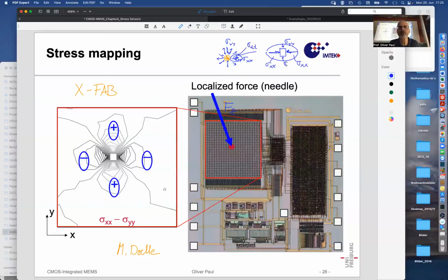And so there is a stress difference of compression in the x direction and in the y direction. That difference, sigma xx minus sigma yy, has a certain sign, and it is negative. Sigma xx is negative, sigma yy is not as negative, so we have a negative value. If we look on the left, same value, negative.